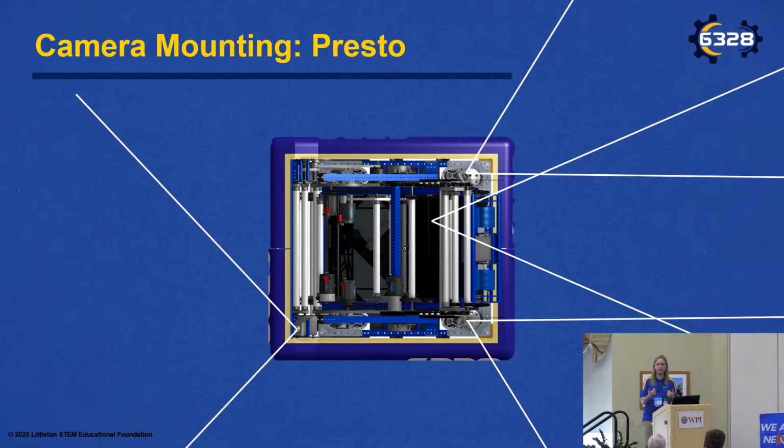That back camera is actually a wide-angle lens, so it's about 90 degrees. A good example of how you shouldn't be afraid to mix up camera lenses and types based on the requirements. Also an important warning here, we're talking about maximizing the total field of view of the vision system, but we should be careful when talking about individual cameras. It's typically a bad idea to go with cameras that are wider than about 100 degrees. The standard camera model, which is called the fisheye model, breaks down above about 100 degrees with really wide-angle lenses, so pose accuracy will tend to be really poor with those. In general, just running multiple cameras that are getting close to 90, 100 degrees tends to work much better than a single very wide-angle camera.